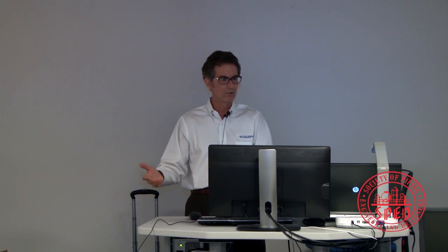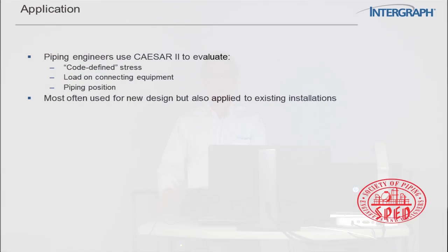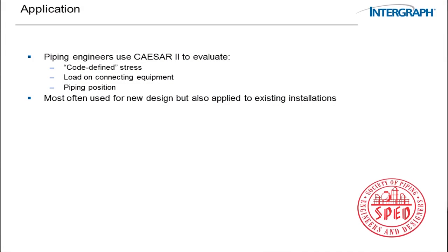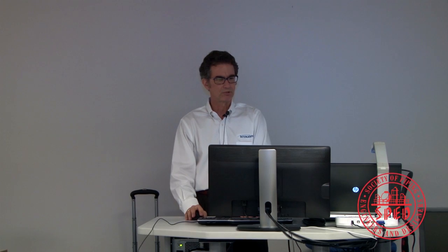So this is where a lot of the work of the engineer goes into making sure there's enough flexibility in the piping system so they don't overload equipment. And finally, you have to know the final position of the pipe as well to avoid clash or sliding off of supports and things like that. So basic structural analysis with code position is also part of the game too.